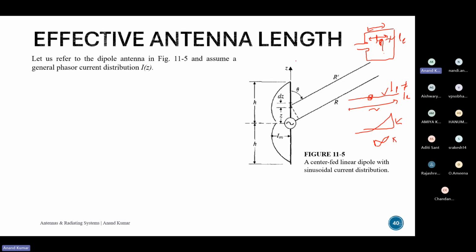And so your question was, there are two antennas and they have the same length, how is the physical length different? What I was trying to say is it is based on the geometry. If you curve an antenna, and if there is a straight antenna, the frequency of operation will change.